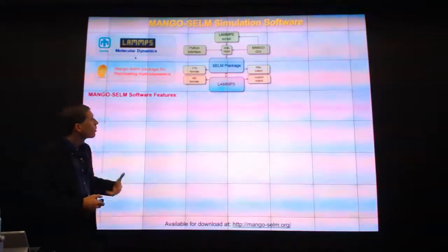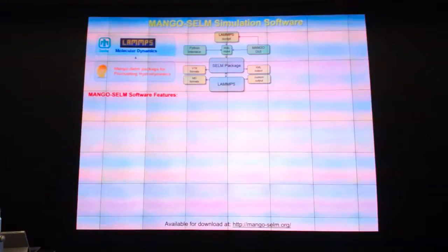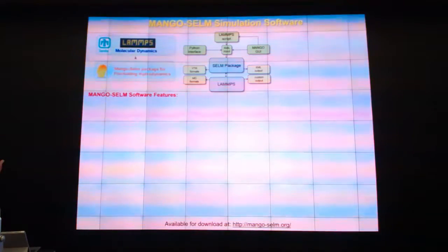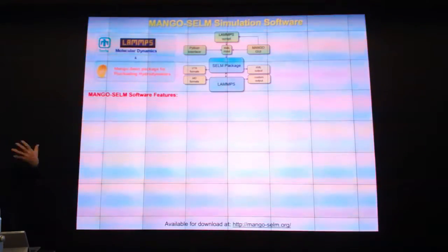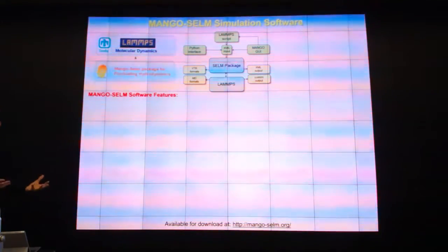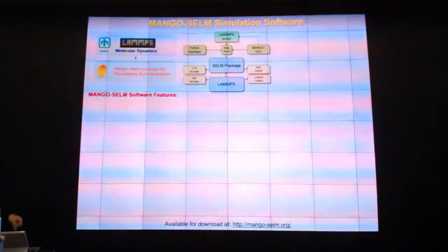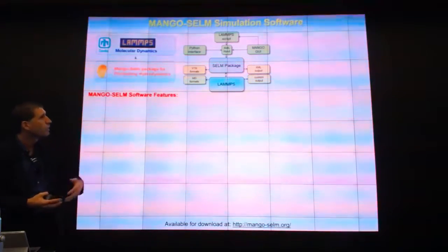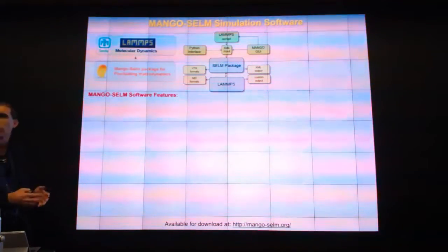And so the way that we're integrating with LAMMPS is we're allowing LAMMPS to take care of a lot of the microstructure modeling part of the problem, right? So if you noticed, you can have a general force law there. Well, I don't want to have to go back and try to do what Steve Plimpton's group can do at Sandia much better, which is things like particle mesh Ewald, which has been highly optimized in k-space based methods, looking at various types of clever algorithms for sorting particles to do pair interactions and things of that nature.